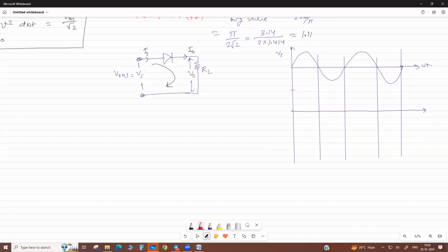So see, here we show the output voltage. Now when a positive pulse comes, this input voltage positive pulse, this diode is forward biased, it conducts. Suppose this diode has forward resistance, but sometimes an ideal diode has zero resistance, so no drop here. Entire pulse as it is we get here in output. Okay, same pulse without drop. So this is the voltage across after the diode. When the input is negative, it is reverse biased, it does not conduct. Then only the positive pulse comes, so it is a half wave rectifier.